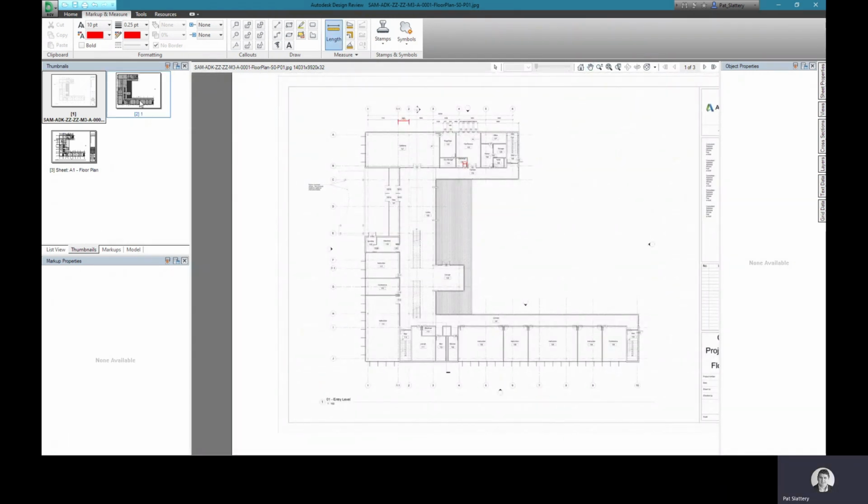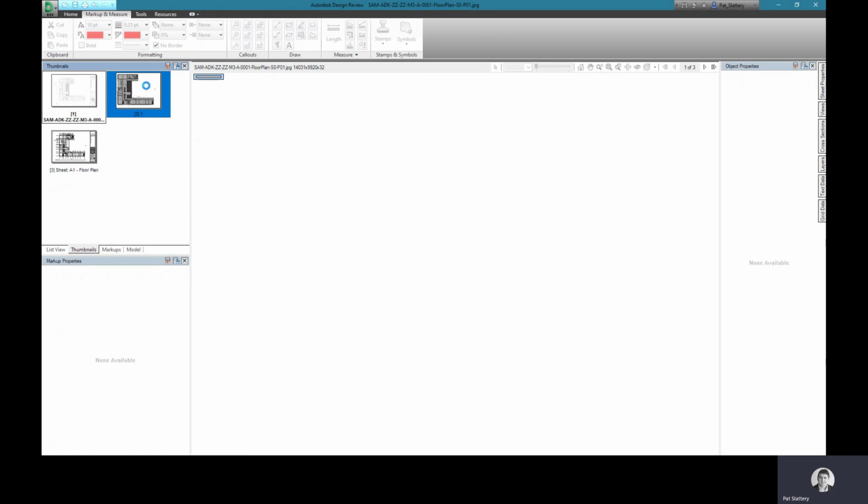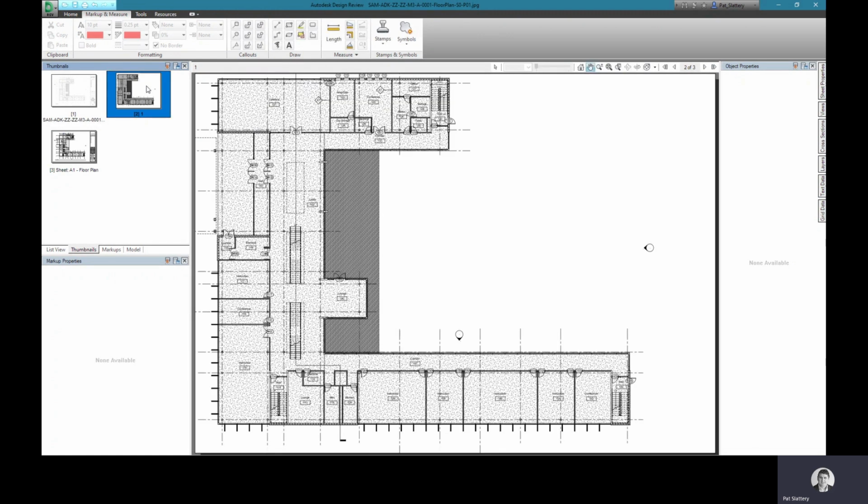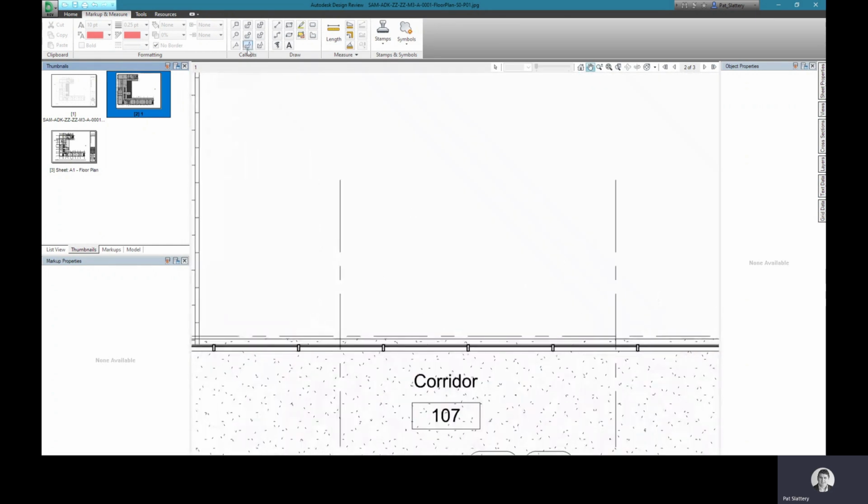The same is true of PDFs. Now, sometimes if a PDF has been plotted to scale from the originating application, whether it's AutoCAD or Navisworks or Revit, whatever people are using, it will come into scale, and you can pick on things. If it's a scanned raster PDF, then you will have to do the same process of scaling the PDF.